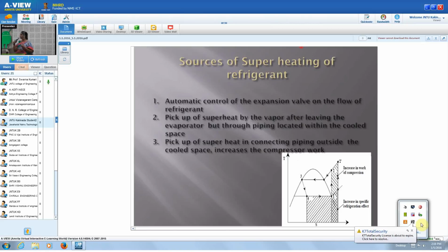So already we have seen when the suction temperature decreases, when the exit temperature increases, and similarly the suction pressure decreases and discharge pressure decreases. So if the pressure varies like that, whenever there is a decrease in the suction pressure and an increase in the discharge pressure, work input will always be more. So last class we have seen it with a number of diagrams also.